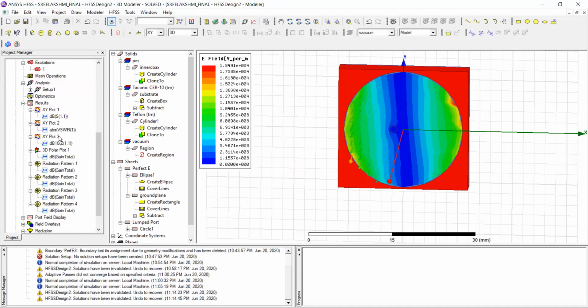There are advantages of circular polarization, like you can actually accept the horizontal and vertical polarizations with 90-degree phase shift. In this case, a vertically polarized antenna can only take vertically polarized waves. A horizontally polarized antenna can take only horizontally polarized waves, but circular polarization can take both the horizontal and vertical.